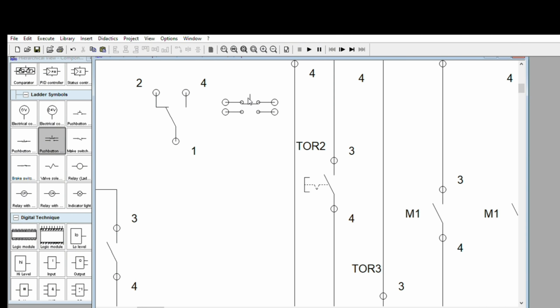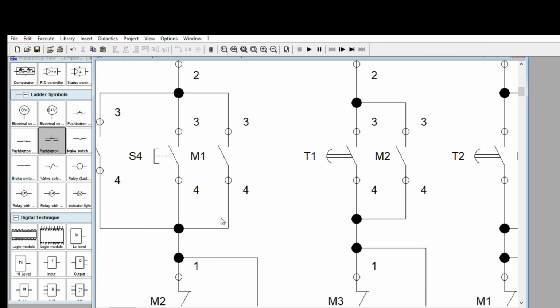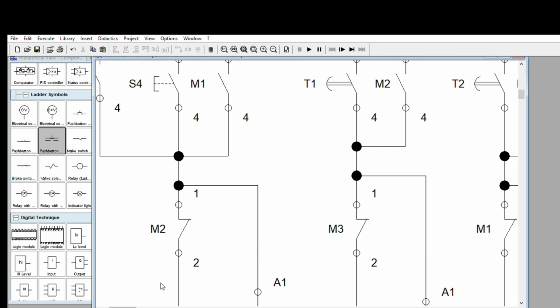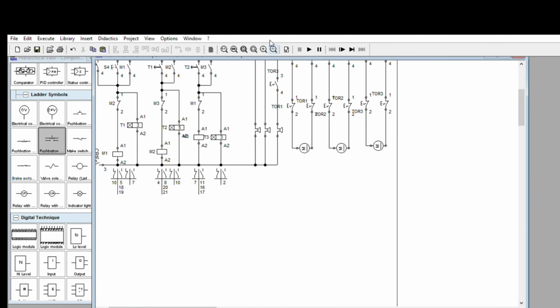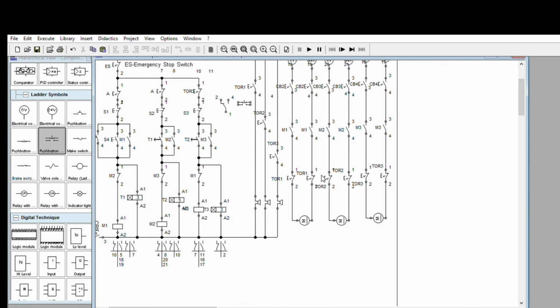So, okay. In this case, we don't need the timer here because we don't have complex motor wiring. We don't have forward reverse there. So no need to add the timer. If you have forward reverse or complex wiring here, well, that will be dangerous. Forward reverse line 1, line 2, line 3 can be short circuited.